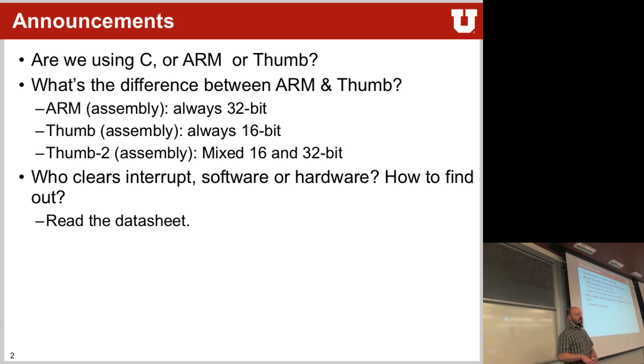Another question that was very important, I think, is who clears interrupts, software or hardware, and how can I find out? And that's really the problem. You don't really know. It really depends on the peripheral and who implemented that particular peripheral. Oftentimes, you have to clear them in software, but not always. So how can you find out? Well, you read the datasheet.